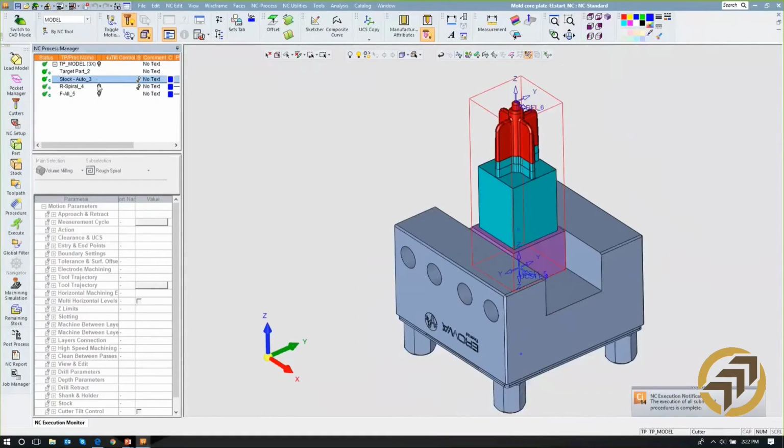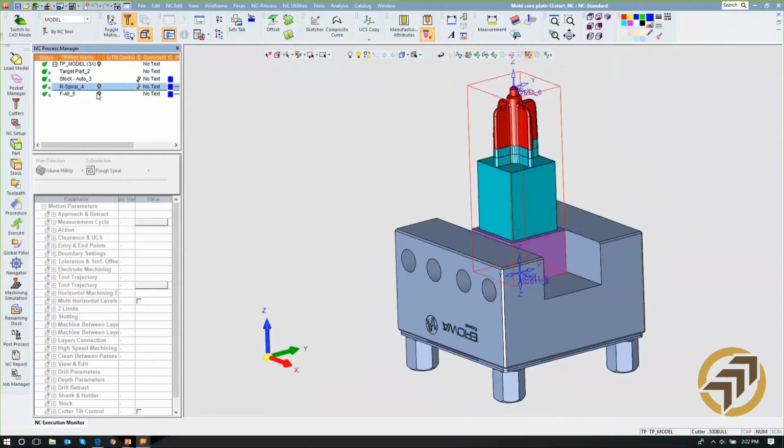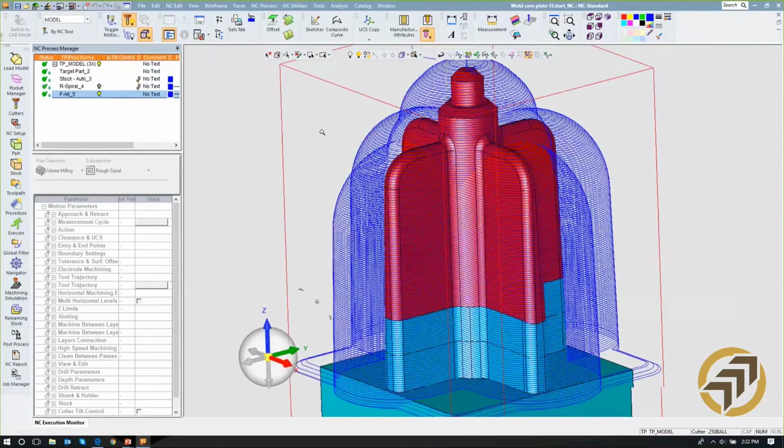So that way it gives it some intelligence to know how to cut. Obviously I would probably not even have the holder there, but just to illustrate that you can control and avoid hitting things that you don't want to hit, or cut useless areas. All right. And there's a semi-finish, maybe a quick ball end mill, wrapping down it to start to get some of that material out.